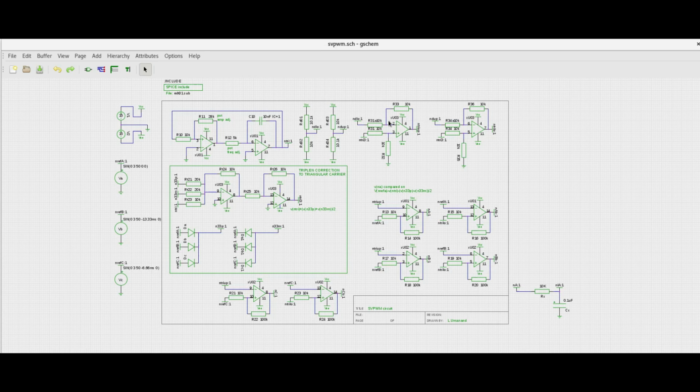These are actually not part of the PWM circuit, because if I have to make a PCB out of it, I need to use only what is inside the page and then put connectors to wherever these items attach. So I have put all these external components for simulation purposes, and what is there inside can be directly sent for making PCB. Now these op-amps, the symbols of them and the models of these op-amps are in edt01.sub. The symbols I have already provided for you in my earlier resource.